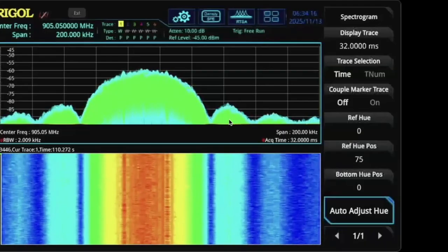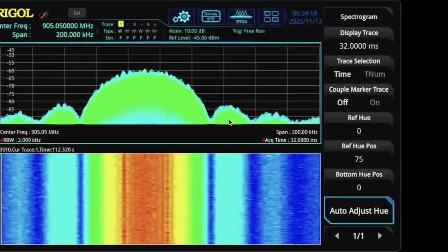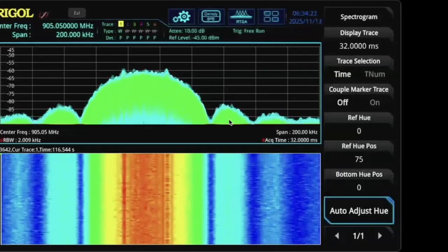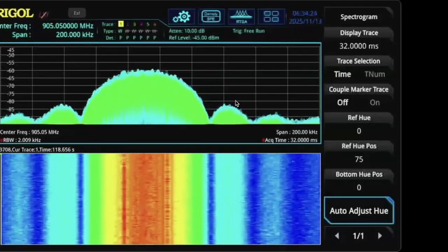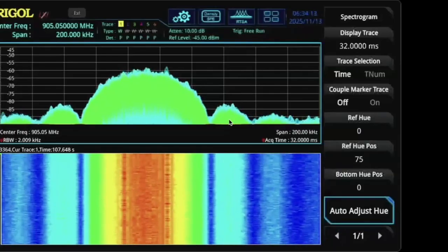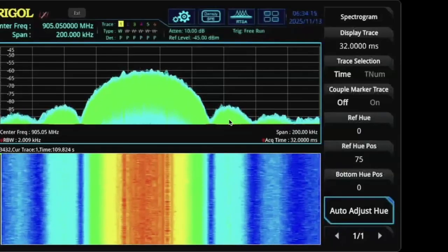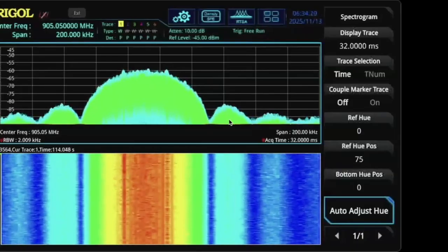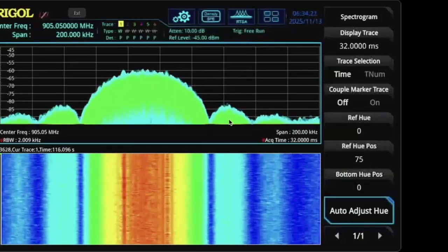We have added our timeline management. So frames are coming out at the right time and never getting dropped there. And in addition to that, the bits that are being transmitted have the scrambler attached. So we're transmitting more or less white data.